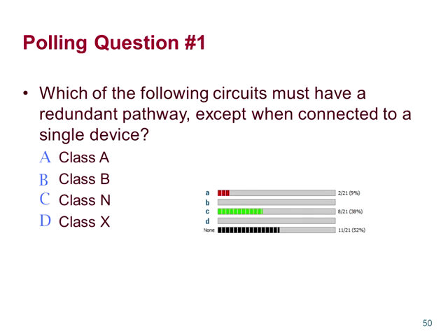It is on slide 33. It has to have a redundant pathway because the connection between the data forwarding equipment is not monitored for integrity. But we do verify communications from end to end. So while we won't get a trouble signal, we will get a communications failure, or we will just keep communicating normally if we have a redundant pathway.